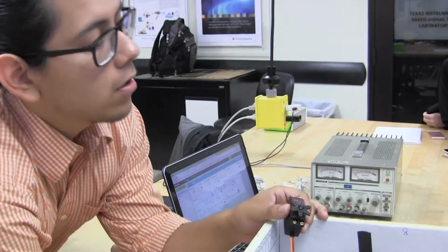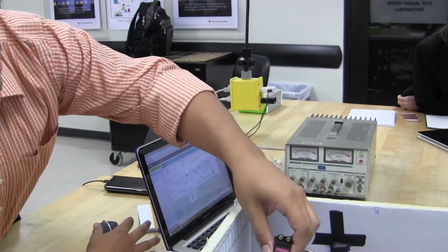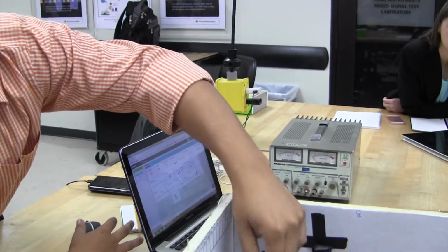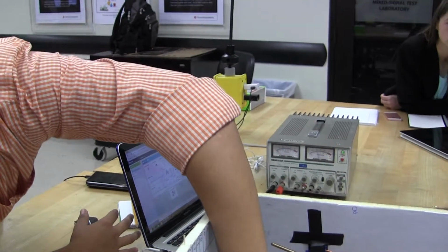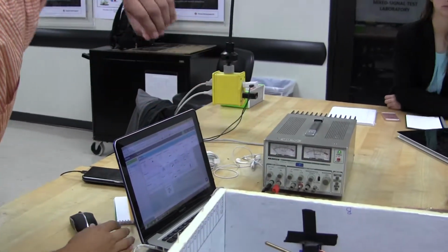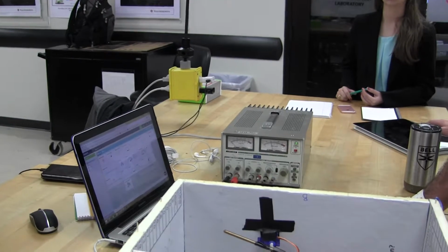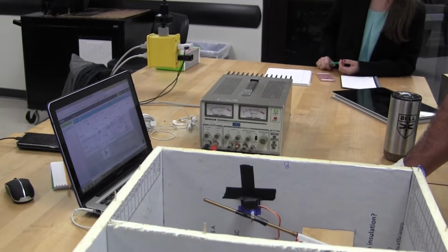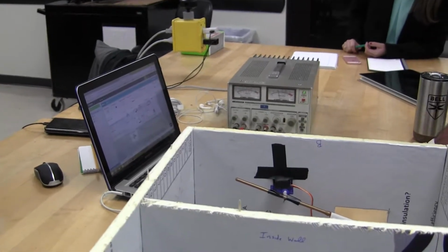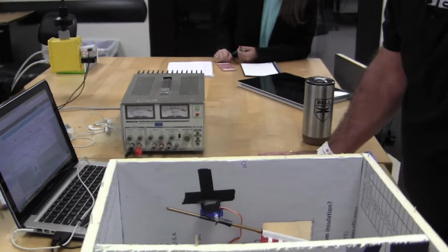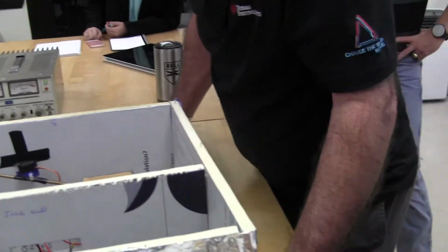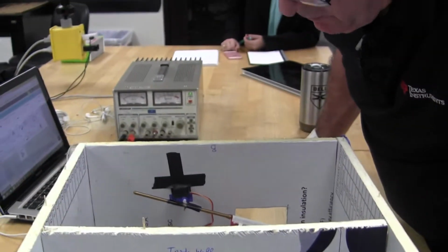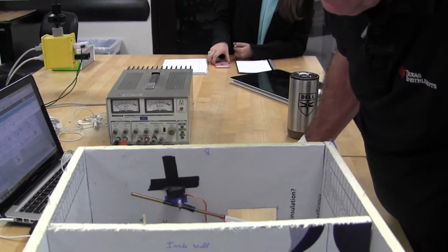Okay, and how much will this board drive? How many servos? No, what current, what load can it handle on each one of the ports? So it's 20 milliamps shared among 16 ports. So 1 point something, however the math ends up, which is why we're using these. So the max power any port can work is 20 milliamps.